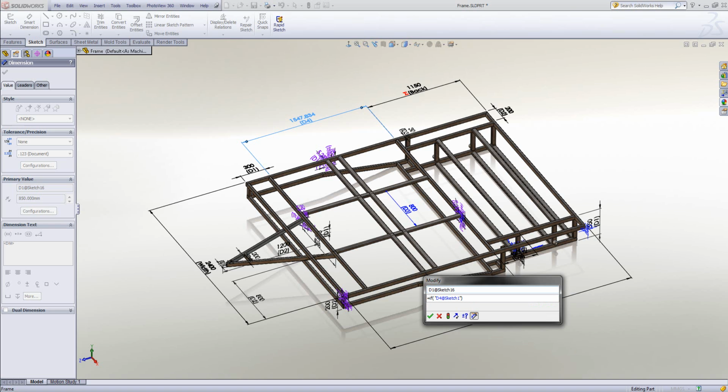So we're going to say that if this dimension is greater than 1650, I want the result to be that the spacing will be worked out for this item. So I want it to be this item divided by 3, or this item, and I'll select in there again, divided by 2. And that should give me the result that I'm looking for and space the items nicely.